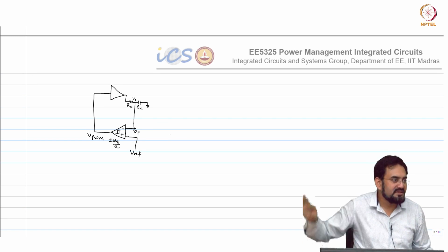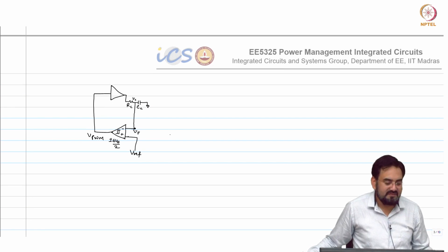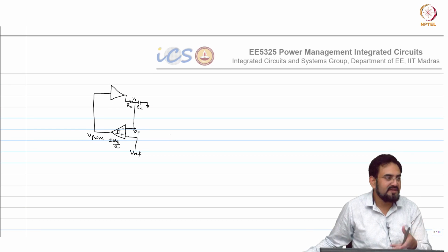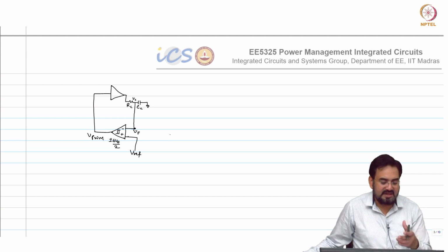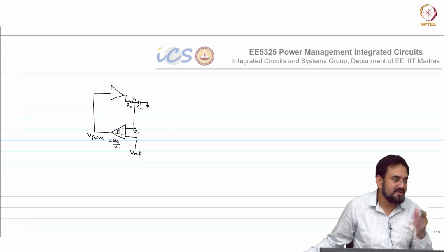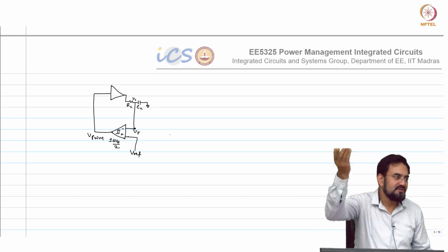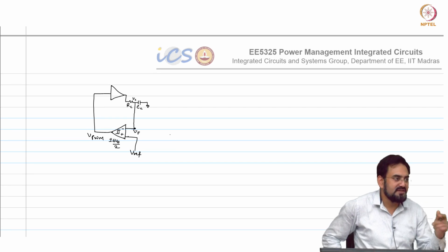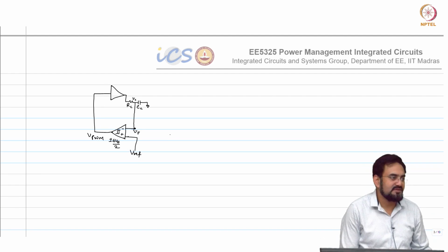Do you remember the triangular ramp generator? We had a charging and discharging current. It is similar, instead of that you have RC here, that is the only difference. As long as your RC time constant is much larger compared to your time period, you will get the same behavior as current charging and discharging that capacitor. So, this is acting as an RC oscillator, nothing else.